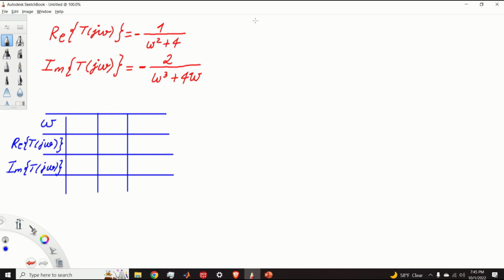And over here, we can just sketch our original complex plane. Here's the s plane, this is the real of s, and this is the imaginary of s. And as I mentioned in the beginning of the video, omega is varied from minus infinity to plus infinity. However, while sketching the Nyquist plot, you don't need to actually vary omega from minus infinity to plus infinity. You can start from 0, from very small positive values of omega, and go to plus infinity. Why is that?